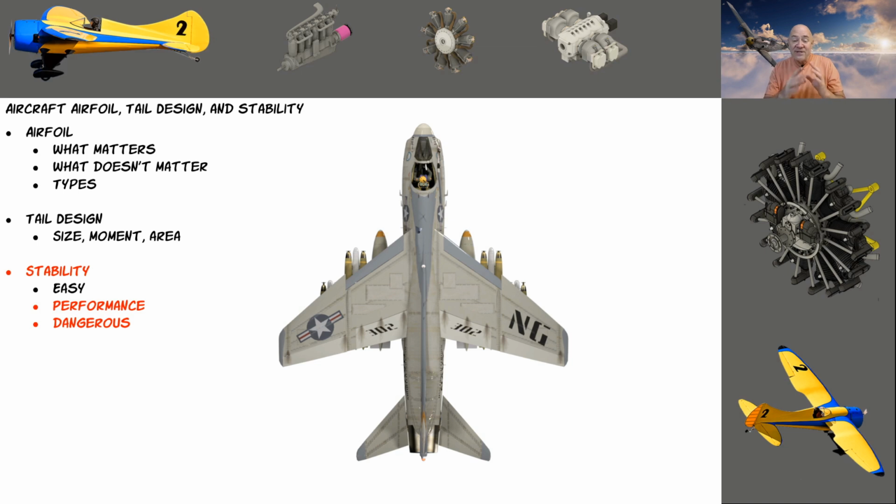The reason I'm saying this is because there used to be, I think it was Jet Hanger Hobbies. I had the 46 size OS version of this, and a friend of mine had one. His flew like garbage until, and this was an old Airtronics radio, we ended up only having about 15 degrees of up on the stabilizer and about 5 degrees down, and it flew on rails. But when he had like 30 degrees up and 25 down, it was almost unflyable. And the CG was actually a little bit nose heavy.